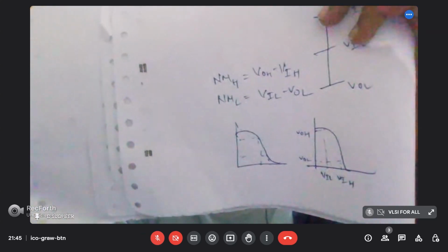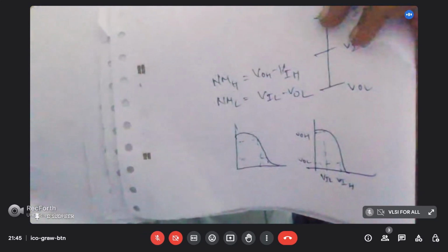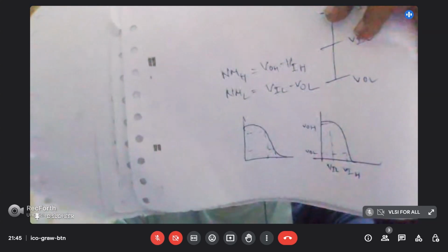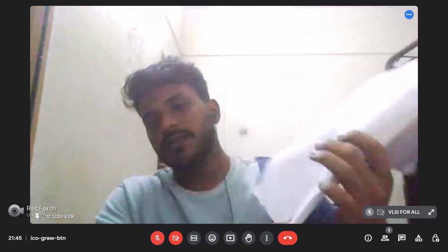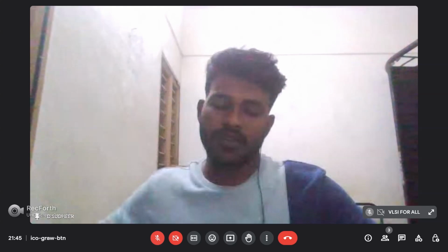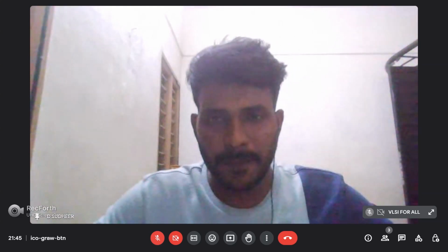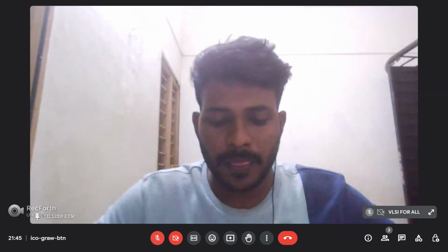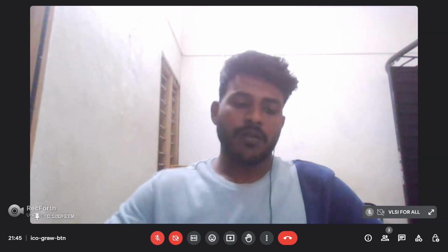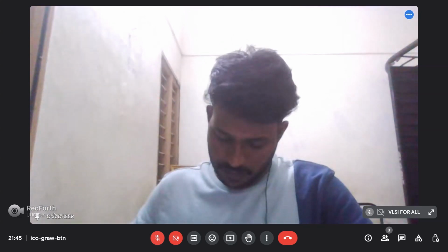VIH is the input voltage high. VIL is the input voltage low. VOL is the output voltage low. VOH is the output voltage high. Okay, tell me why we are unable to achieve exact 0 or exact 5 volts in our CMOS circuit.